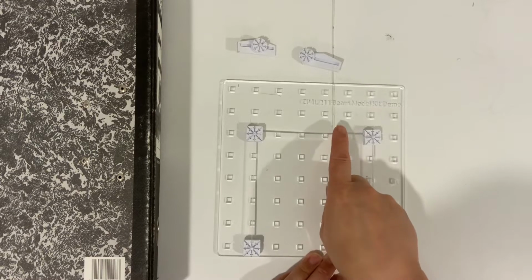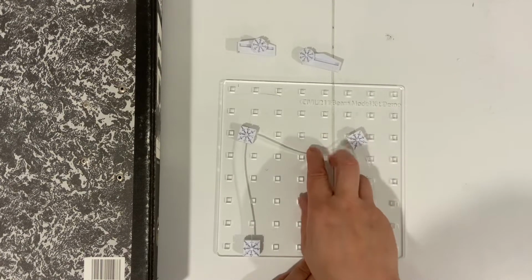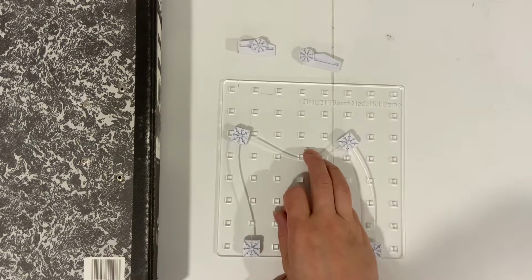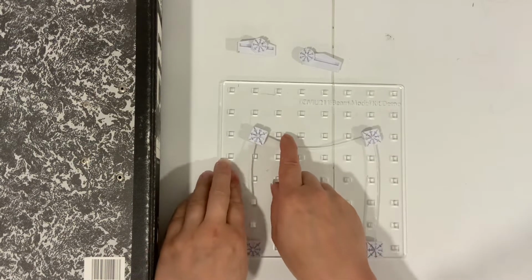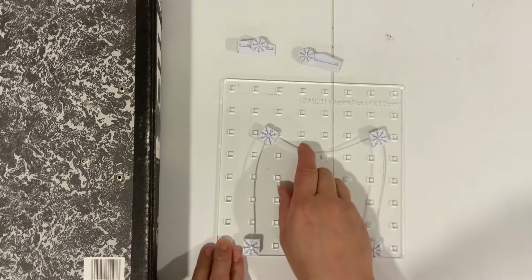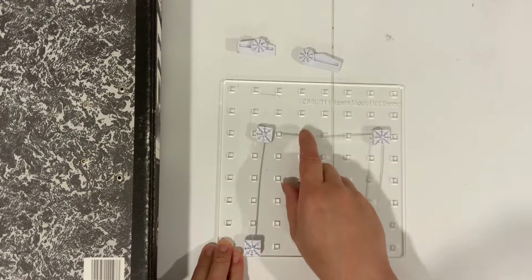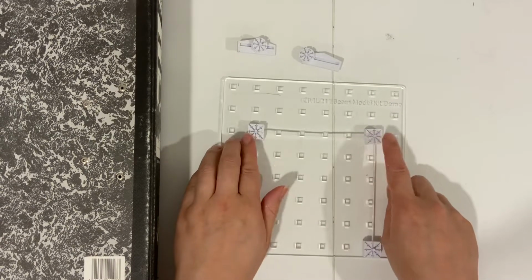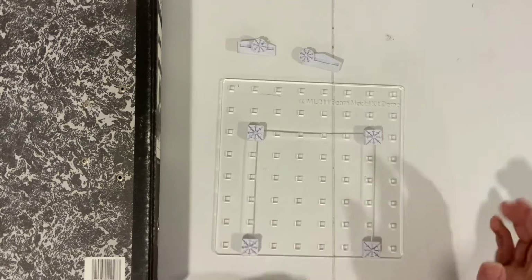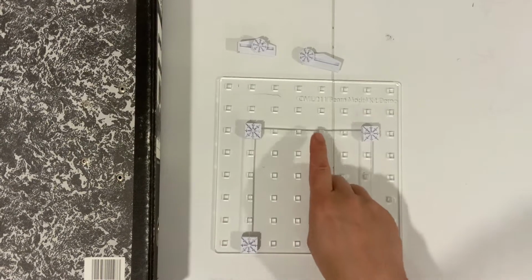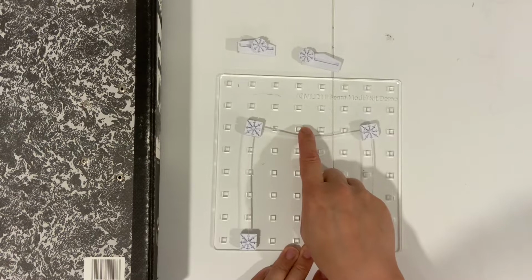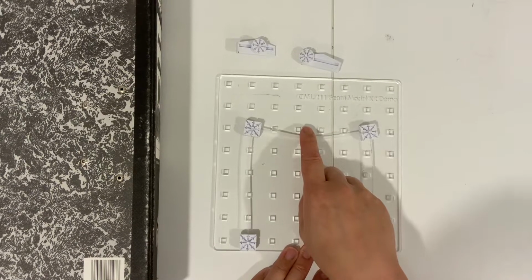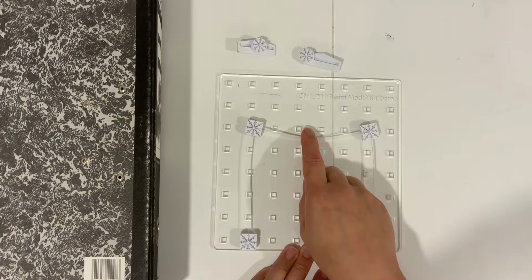Now, as I said, if you put the load there, there would be a tendency for the frame to want to sway to that side. And if you put the load here, there would be a tendency for the frame to want to sway to the right side. So as soon as the load is asymmetrical, the frame would have a tendency to sway to the left or to the right. But if the load was put right at the center, then by symmetry it's not going to sway to the left or right, if you can see that. So I've applied the load and you can't see it swaying to the left or the right, so it's not swaying, as you can see there. So we'll just leave it there.